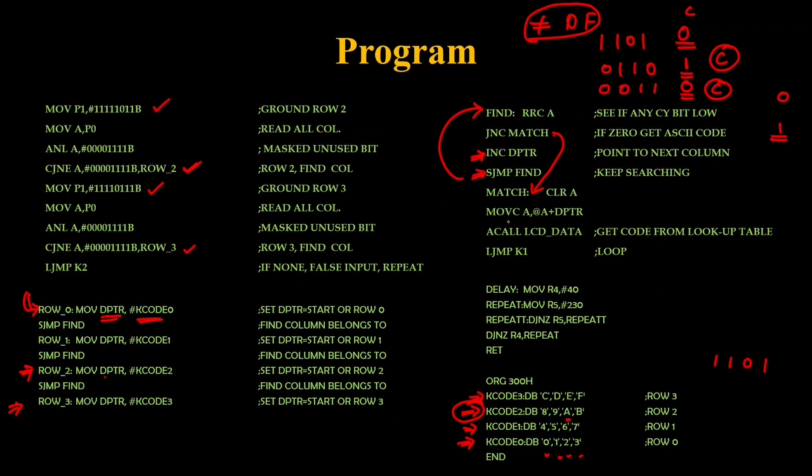So what will this instruction do? Already in terms of your accumulator, I am having some values, right? So it is going to be accumulator plus DPTR, clear your accumulator, right? So I have cleared my accumulator. So 0, 0 is there, plus your DPTR value is going to be 0, 1, because this is the value which I have identified, right? So the memory location is going to be 0, 1, right? So if it is going to be 0, 1 in that condition, how is it being done?